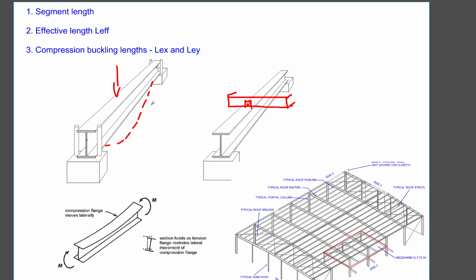This beam is going to sag. So you have to think about the behavior of the beam sagging. For a beam like an I beam, it's not going to sag as a pure vertical sagging, and it is actually not. What it does is not only sag, but also twist and bend sideways. It's just like if you bend a ruler, it's trying to bend sideways, plus a little bit of downwards, if that makes sense.